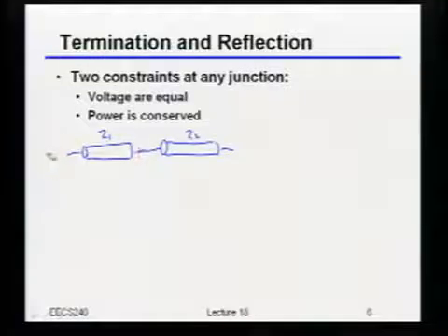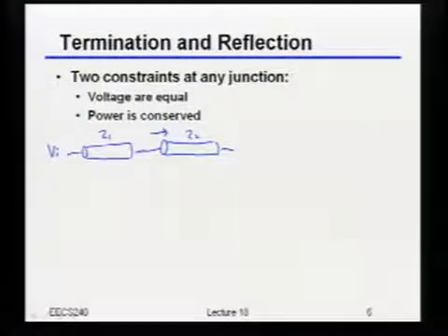Okay? So in order to do that, and again, this is hopefully review, but remember, essentially, what's going down that transmission line is like an electromagnetic wave. Okay? So anytime that wave sees a discontinuity, basically two things can happen. One is that some piece of the wave will get transmitted forward into the next transmission line, and some piece of it will get reflected back.